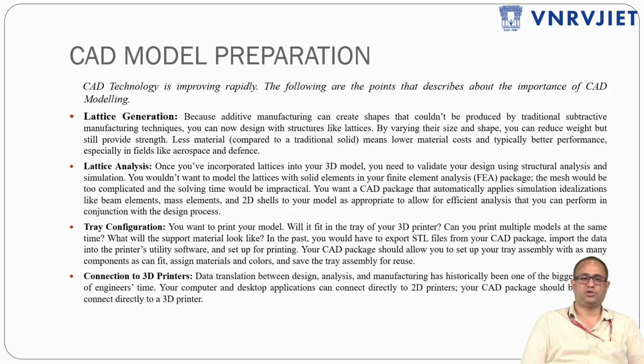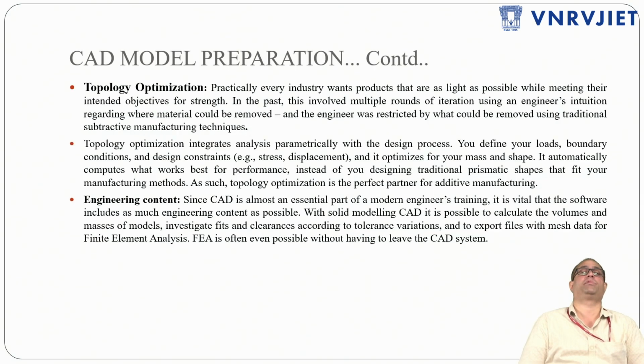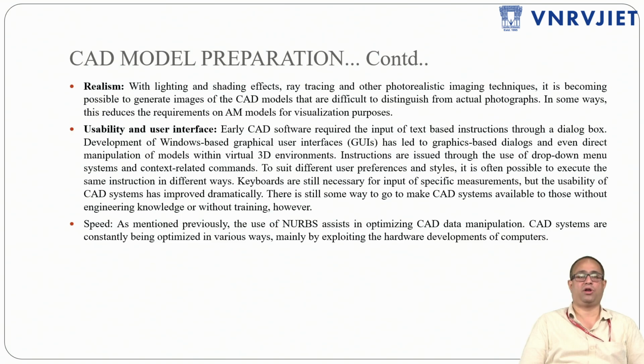These are the points to keep in mind when you work with a CAD model for additive manufacturing, not just simply doing a CAD model and an assembly. It is not enough. So consider how well you prepare the CAD model for AM: lattice generation, lattice analysis, tray configuration, followed by topology optimization. These are the essential points to keep in mind to generate a CAD model.